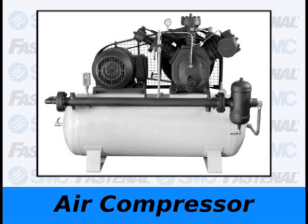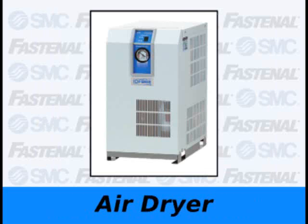If your customer has an air compressor in their facility, there is SMC business there. SMC doesn't sell air compressors, but you can think of SMC as everything after the compressor. The problem with air compressors is the air comes out very hot, and as it cools down, a lot of moisture condenses. If you've ever run your car air conditioner in the summertime, you may have noticed water dripping on the driveway. Moisture in air lines can cause many problems, so an air dryer is needed.